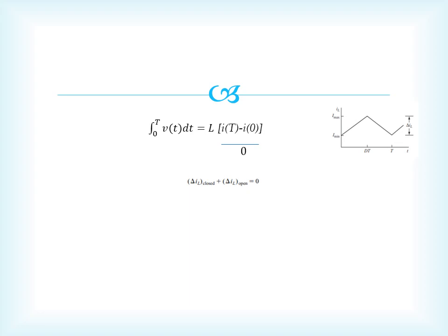You can see from the waveform also that delta IL closed is equal to delta IL open for every inductor circuit which is in steady state. This condition is also true.